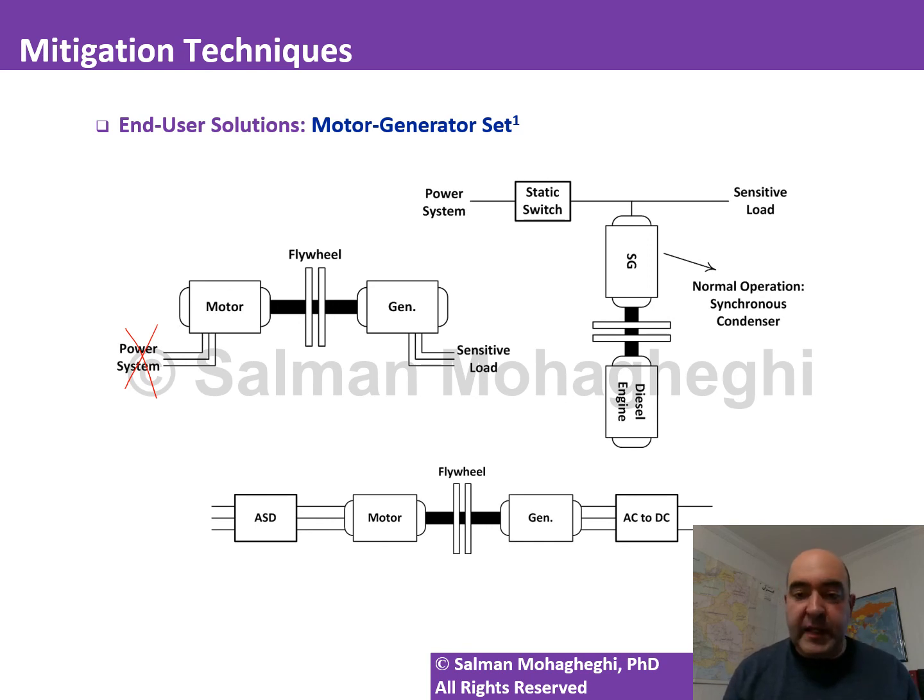If the load, for example, can tolerate up to 20% of drop in frequency, it can run for a longer period of time. However, if the load can only, let's say, tolerate up to 58 hertz, that means you can have a shorter period of time where this generator is going to be effective. The moment it slows down beyond, let's say, 58 hertz, then this frequency that it provides for the load is not sufficient anymore, and the load has to disconnect.